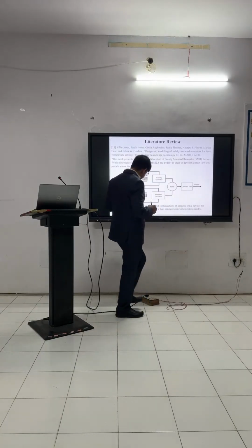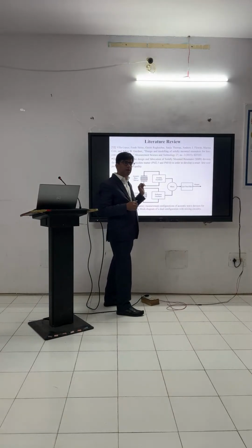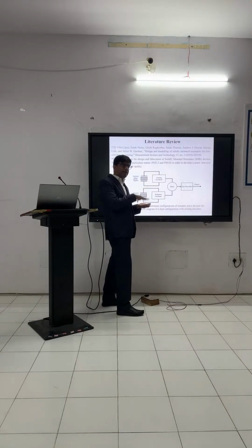Clear? So what will happen, for example, if you have exposure of carbon monoxide gas over the sensor? Nothing will happen to the reference device because there is no sensing layer there. But in this device, you have a sensing layer. So there is absorption of that gas onto the sensing layer, and due to this absorption, mass loading happens to my resonator.